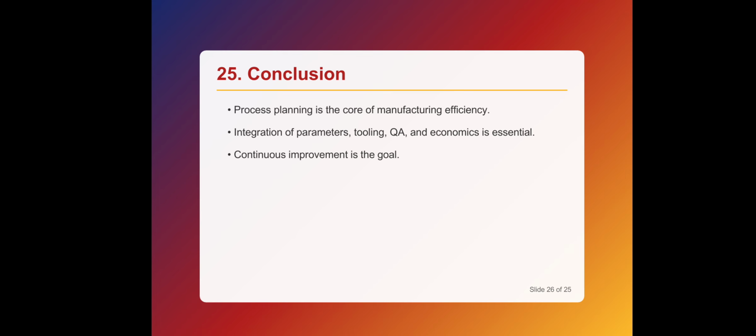So for calculation of processing times, the appropriate set of machines required is selected. The next step in process planning is to calculate specific operation setup times and cycle times on each machine. Finally, with the calculated cycle time, appropriate machine rates, that is the cost of machine ownership or use in rupees per unit of time, are applied to calculate the expected standard cost for the given operation. So the documentation is very much important, as I told earlier.